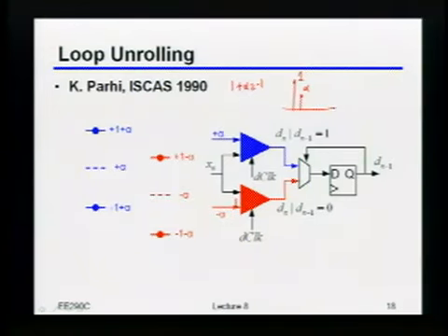Okay, so I wanted to spend a little time on what these different levels look like, because you'll sometimes see eye diagrams with these loop unrolled DFEs. By the way, in communication terminology, this is sometimes called a partial response channel, meaning that you're not canceling all of the response, but you're leaving some amount of intentional ISI there that you're going to deal with later.